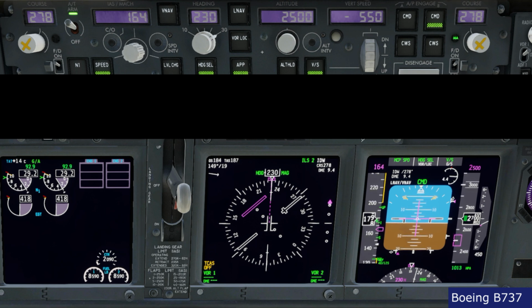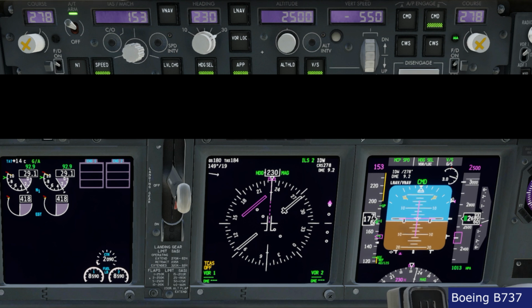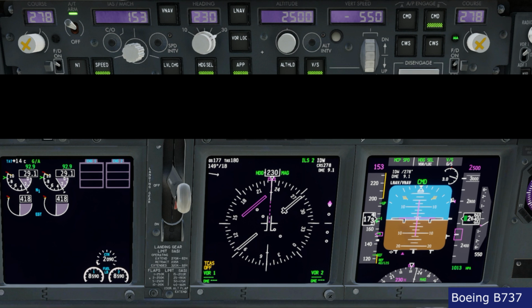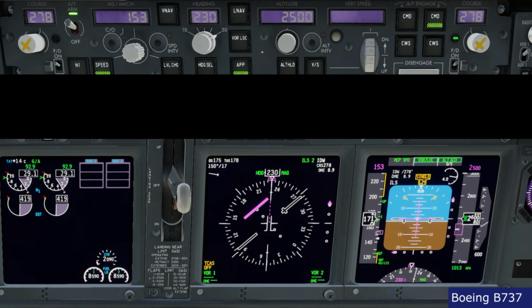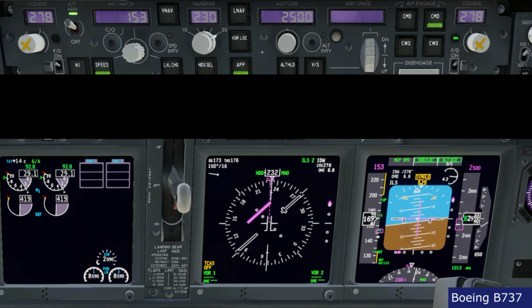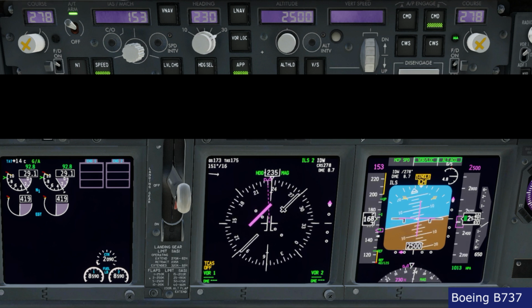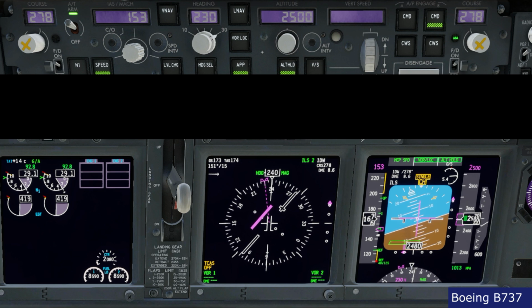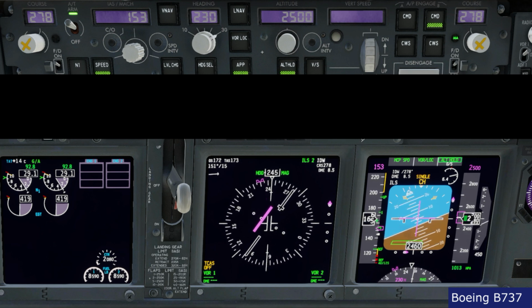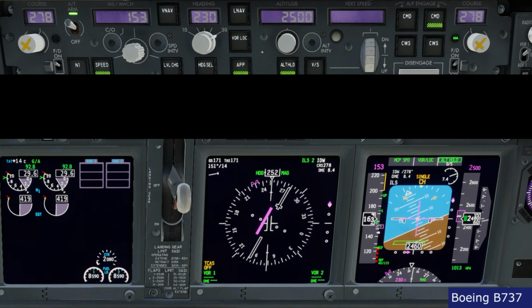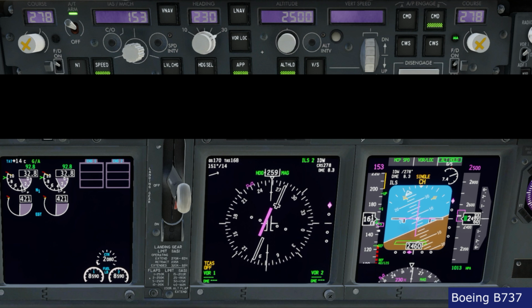You see that we are approaching 2,500 feet. What will happen obviously is the engagement of the transition phase, so altitude acquire is going to come in a moment. There we go. And after the altitude acquire, we will be in altitude hold 2,500 feet. If I select a different altitude at this stage, we will go in vertical speed. I have to wait until we have alt green, altitude hold. Now we have altitude hold. I can select whatever altitude I want.